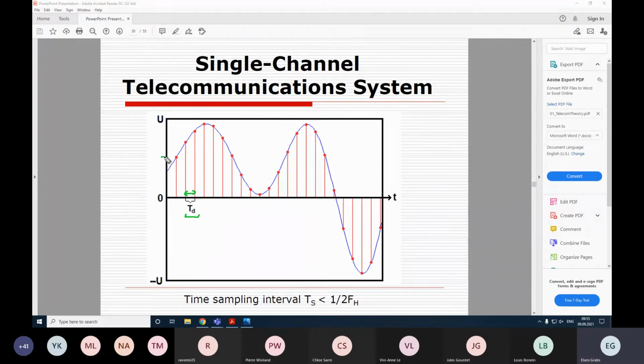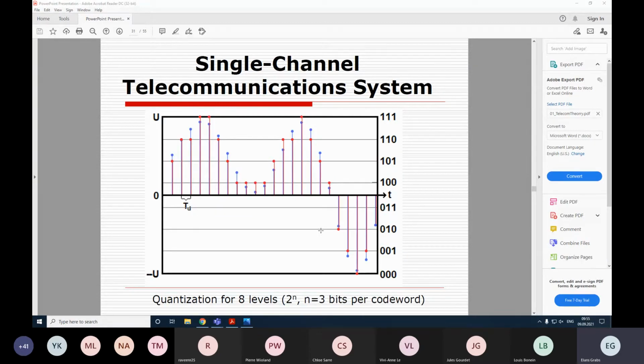It's easier to know that after a certain amount of time you're expecting a new sample of data. Currently the level of these samples is still the voltage, without any changes. So this signal is called a discrete signal. This is not yet a digital signal, this is just a discrete signal, which exists only at specific time moments. Its amplitude, however, wasn't changed in any way. Now, if we perform a similar operation on the amplitude, called quantization, then we obtain a digital signal.